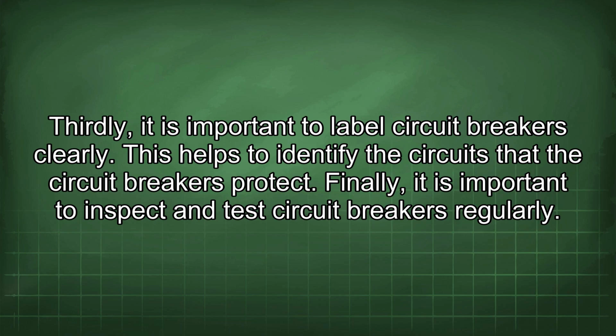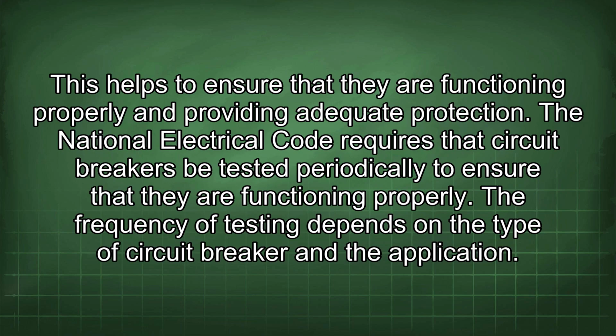Thirdly, it is important to label circuit breakers clearly. This helps to identify the circuits that the circuit breakers protect. Finally, it is important to inspect and test circuit breakers regularly. This helps to ensure that they are functioning properly and providing adequate protection.